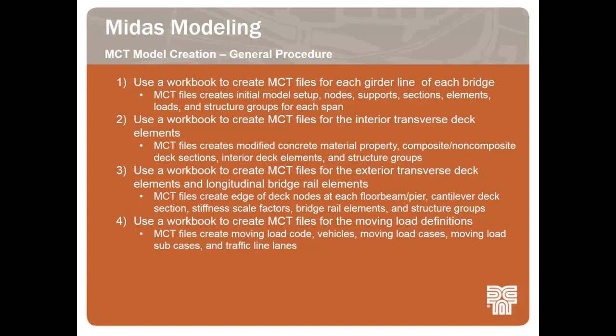The final step was to use the same workbook used for step 2 and 3 to define the moving load parameters. The MCT file created the moving load code, vehicles, moving load cases, moving load subload cases, and traffic line lanes.